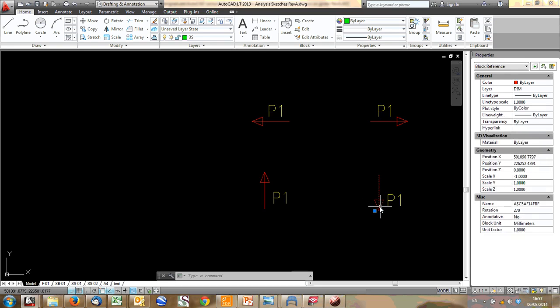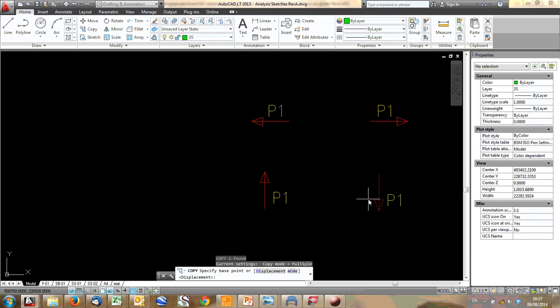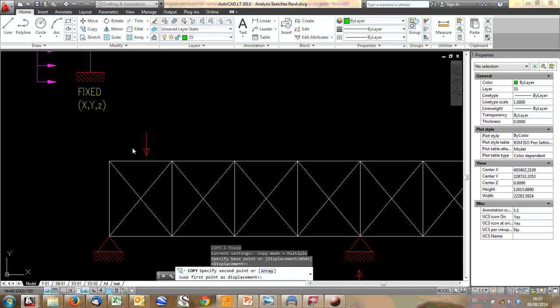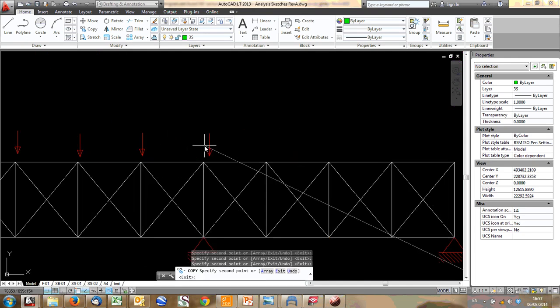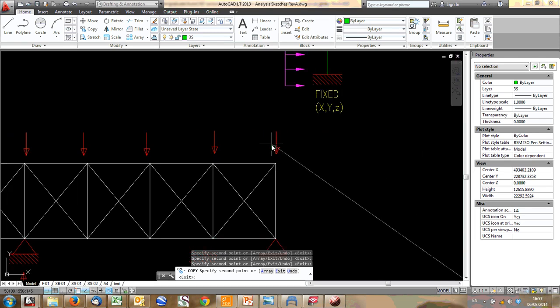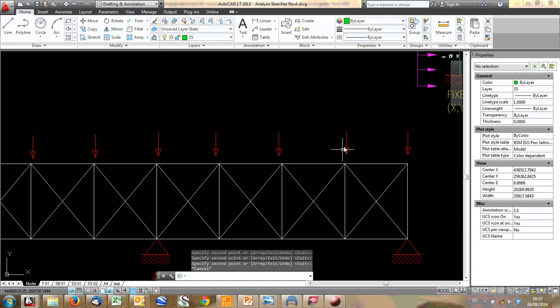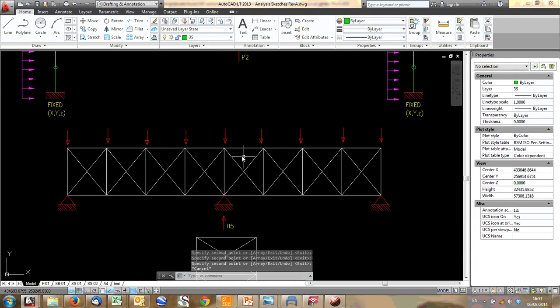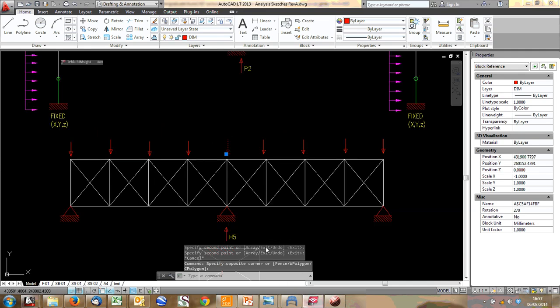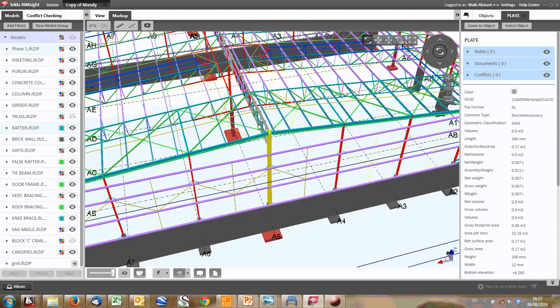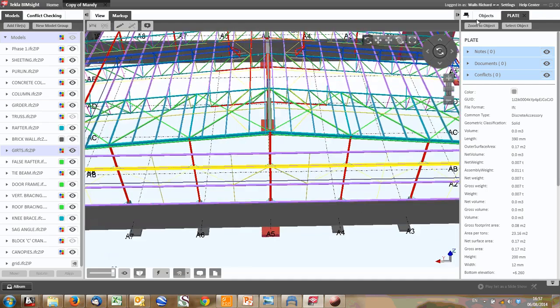If you've got all your loads coming down from your gable columns on top of it, let me show you that. So you've got all your gable columns loading this structure, or you could possibly otherwise put a UDL. But with these long spans, it starts getting a little bit more difficult to do that. You can analyze this one, just be very careful if you add this one in. Don't double count it, so that you add it again when you analyze this model, or you leave it off the model and then you add it separately as a UDL on this column.